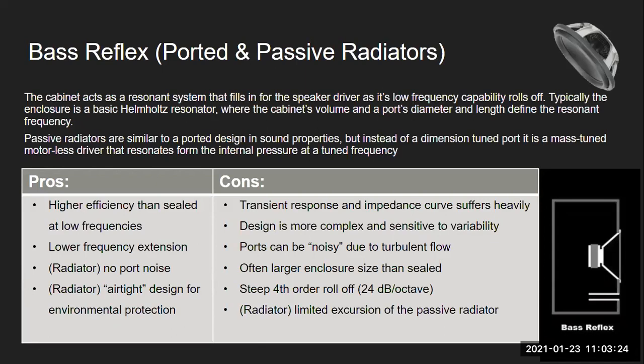You can use the cabinet as a tuned device, just like a Coke bottle, right? You excite it with your breath and you get a tone out of that. In this case, instead of your breath, you use the speaker driver, and the port then starts taking over as the driver starts dropping off.